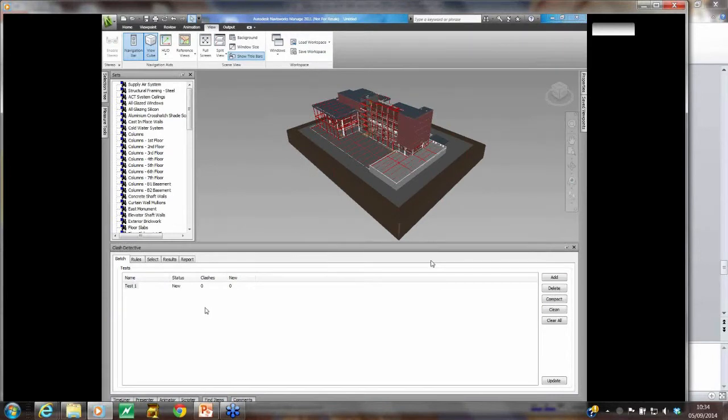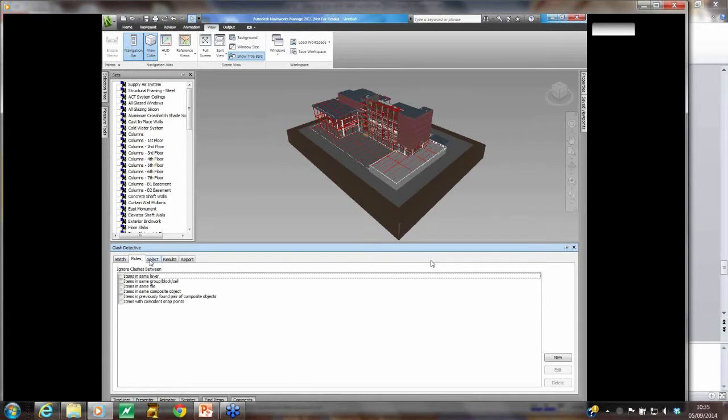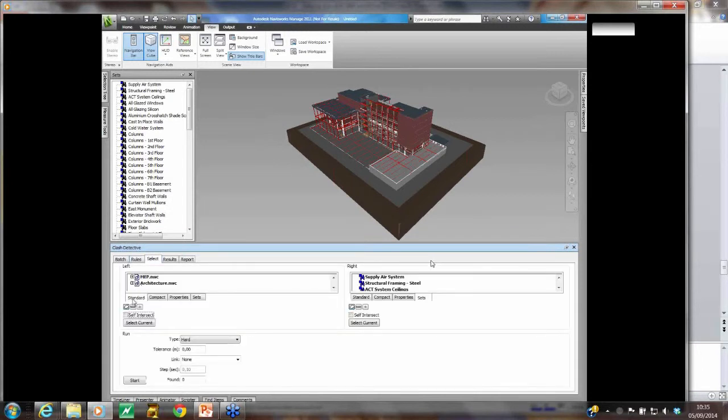So here we're going into yet another aspect of Navisworks, the clash detection. We have the ability to select aspects of the model via those selection sets that I referred to twice now. So we can choose parts of the model via the sets. In this case, it's going to be the structure versus the building systems' HVAC system. So we're picking on the structural framing within one aspect of the model and the building services elements within another, and then ask it to do a clash.